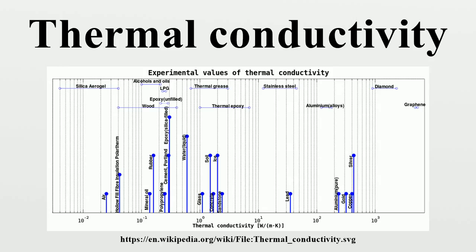Transmittance. A third term, thermal transmittance, quantifies the thermal conductance of a structure along with heat transfer due to convection and radiation. It is measured in the same units as thermal conductance and is sometimes known as the composite thermal conductance. The term U value is often used.